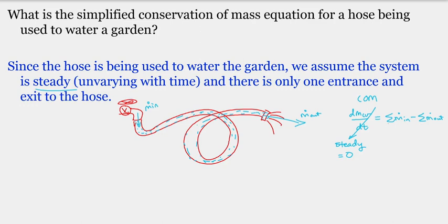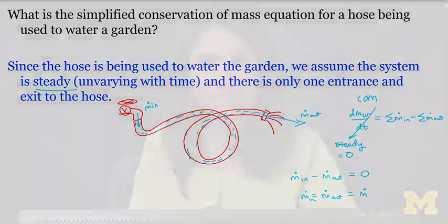And you can say, hey, each of these summations can be simplified to one term entering and one term leaving. And what we see is that for this simple system, there is only one flow rate in the system because m dot in, the mass flow rate in, is equal to mass flow rate out. And so we could even drop the subscript notation. Okay? So again, we're going to gentle our way in. We'll increase the complexity of the systems as we go along.